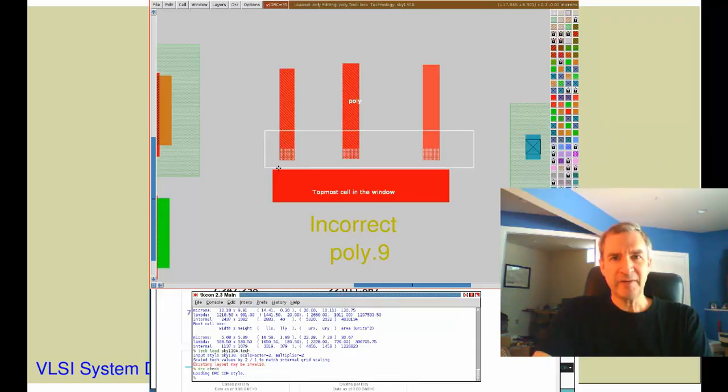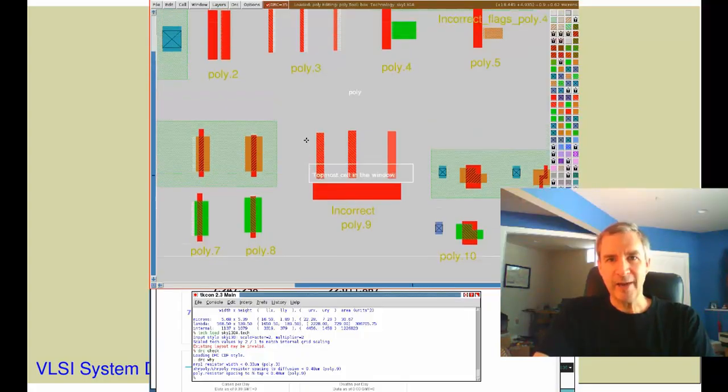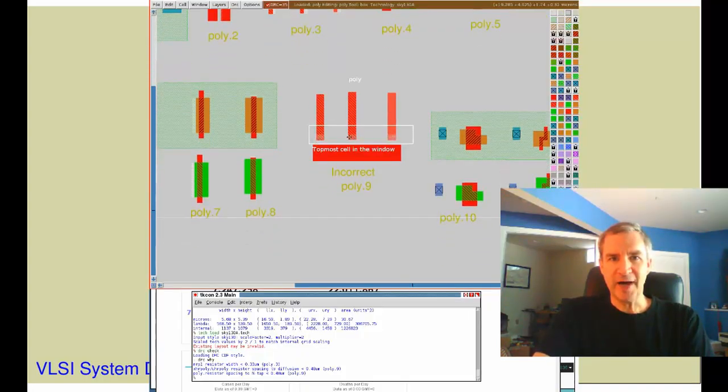But is the rule really completely fixed? Note that the rule said that it was for distance from a poly resistor to poly, diff or tap. I just implemented the rule for poly, but what about diffusion and tap? Actually, there's not even a diagram for this. It was accidentally left out. Let's fix that.